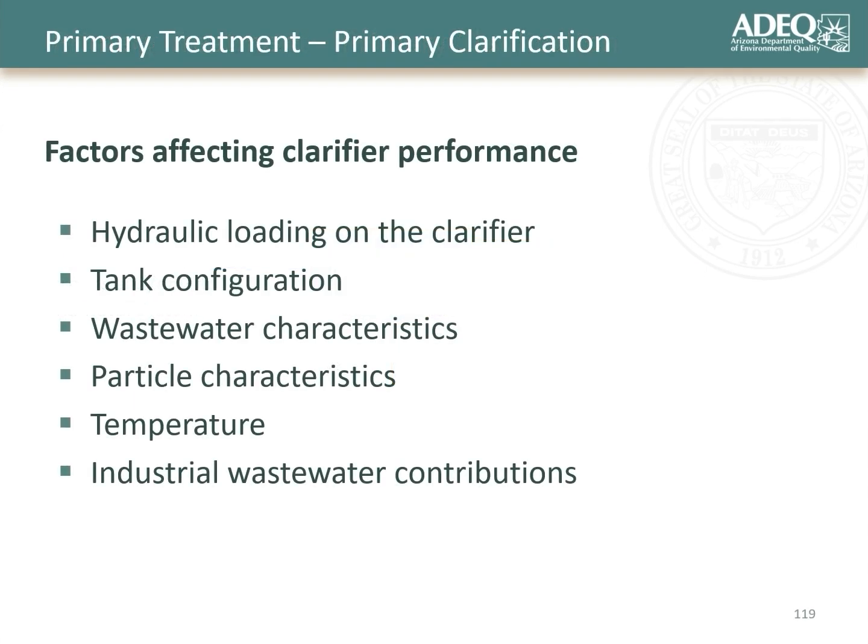Let's look at different factors that affect clarifier performance. Number one, of course, is hydraulic loading on the clarifier. Each clarifier is designed for a maximum volume that it can treat per minute, per day, whatever it is. If you load too much into the clarifier, it can cause short circuiting, and it can also cause washout of solids that are present there. Number two, tank configuration. If you don't have proper baffling, energy from the water coming in can cause solids to be scoured and released and leave the clarifier. That can impact it as well.